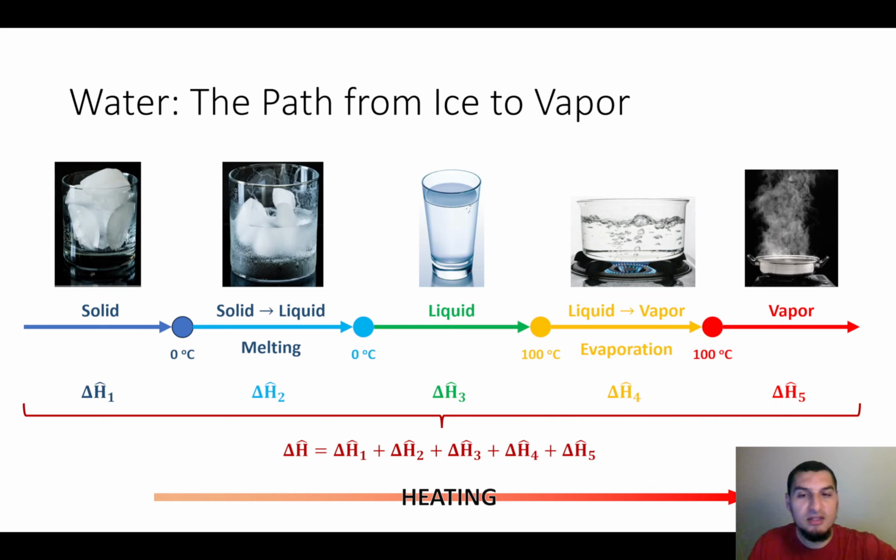And now you can appreciate what the steam table is doing for us. In the steam table, you didn't even care about all these things. You just pick the enthalpy here and the enthalpy here, and you are done. It's as simple as this. But when you do the calculations manually, you have to go through all these steps one by one, which is not a very fun thing to do.